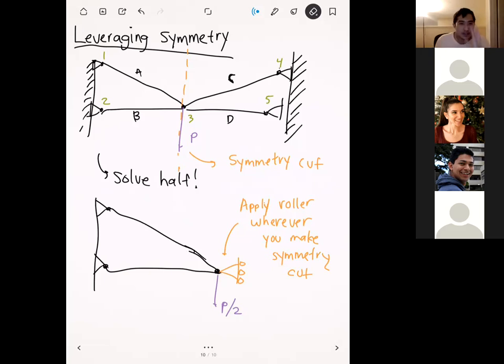And so what that tells ANSYS is that on this face that you're applying this symmetry boundary condition, you can have a displacement that goes in the plane of that symmetry. But you can't have any displacement that goes past into that plane. And so that's basically what's happening under the hood when you apply a symmetry boundary condition in ANSYS. And with hand calculations with direct stiffness, this is how you would do it by hand. All right. Any questions on this?